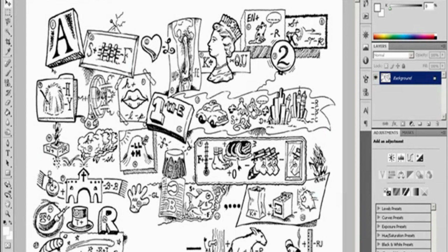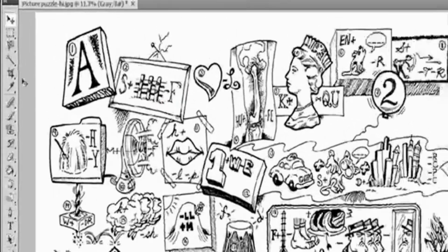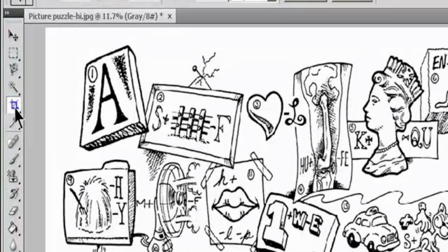Crop images. Crop an image using the Crop tool. 1. Select the Crop tool. 2. Optional: Set resample options in the options bar. To crop the image without resampling (the default), make sure that the resolution text box in the options bar is empty. You can click the Clear button to quickly clear all text boxes.